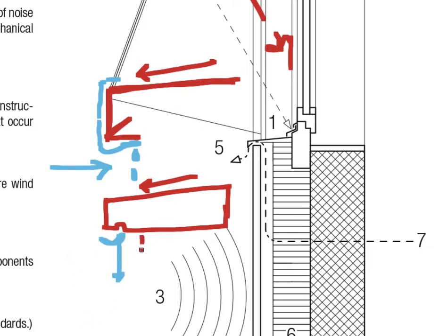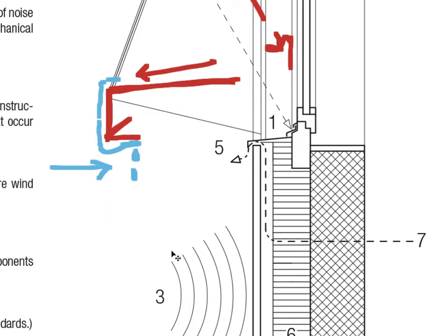The facade would probably be somewhere on that layer. So you have a little bit of a distance between that very controlled raindrop that's coming down and the actual envelope, therefore making sure that your facade material is not just getting completely soaked up. On the one hand, it can lead to damage, or it ages much faster. You could have algae grow there because it's always moist, but it's also an aesthetical thing, because all of a sudden your facade is always wet, and it looks different or not very nice. So water management, one of the most important things to keep in mind.